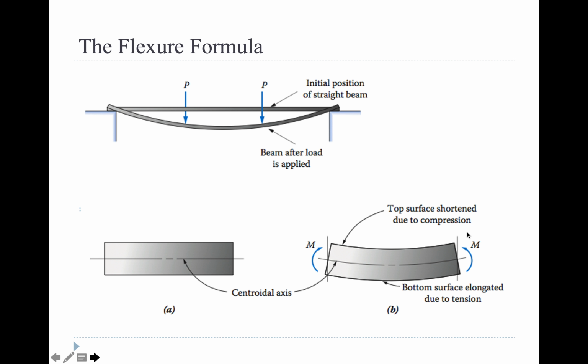So when something's bending like this, it has both compression and tension happening at the same time. And notice here's this centroidal axis, right in the middle. Okay, that's also referred to as the neutral axis. And since it's compressing on the top and tension on the bottom, well, in the middle, they cancel out and nothing is happening. There is zero force at the centroidal axis. That's why it's called the neutral axis. There's nothing happening there. There's no force on there. So designers use this principle to their advantage in knowing that there's no force happening right there. It's balancing out. So they might strategically place things there in the centroidal axis so that there's no force on it and it'll be okay. Doesn't always work out that way, but we know that principle.